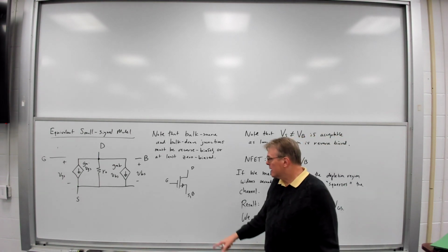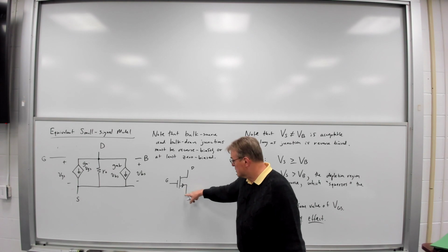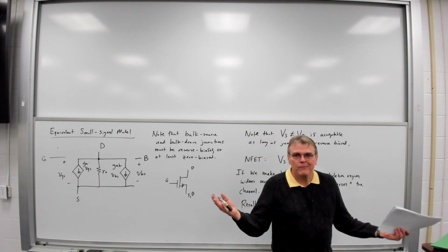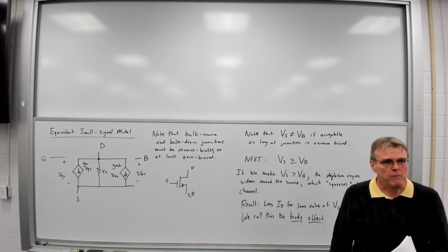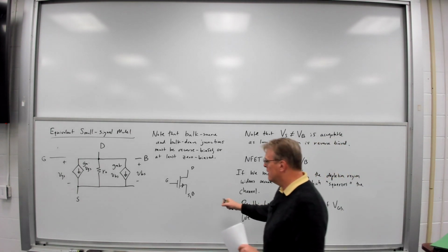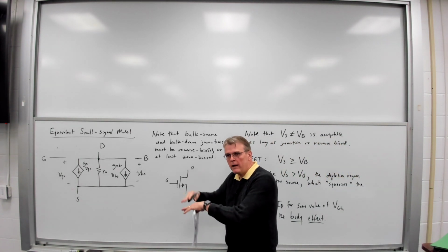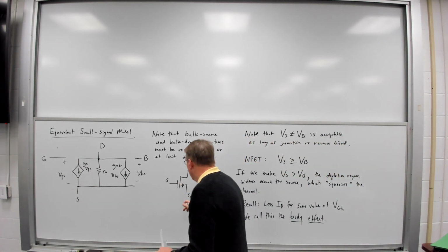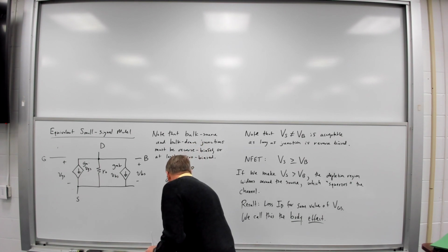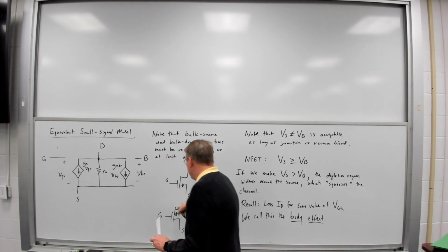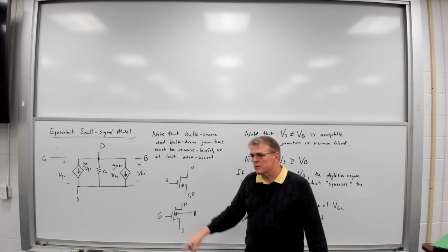And since typically we are normally going to take transistors and just connect the source and the bulk together, it's not really that big of an issue. But if we do have circuits where for whatever reason we are separating the source and the bulk, and we're drawing this instead as a 4-terminal device, in this case, that is a small signal model you have to use.